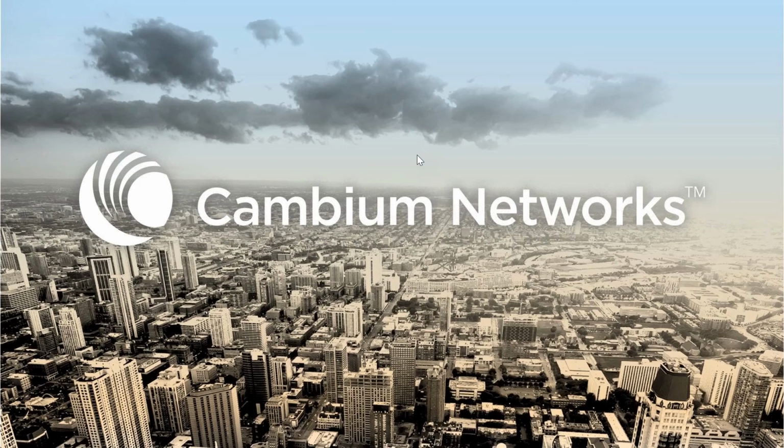Okay, 820 and 850 radios, yes, you can power them on. We are in beta with this product now. The 850 is on our list of being able to be powered up. But let me catch myself there: if the 850 takes PoE, meaning it can be powered over Ethernet, then the answer is yes. And this is the same answer for any third-party device. If it can power up over PoE, we can power it up. If it takes separate power, like an AC cord or a DC input, then no, they have to supply their own power. But if it takes PoE, we will power it up.